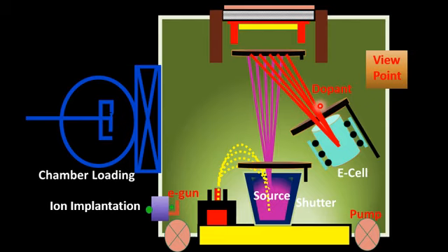As I previously discussed, MBE is a multi-component system. It consists of many types of characterization setups as well as many types of vacuum-based systems. There is also another setup which is common in molecular beam epitaxy, known as mass spectroscopy or mass spectrometry.